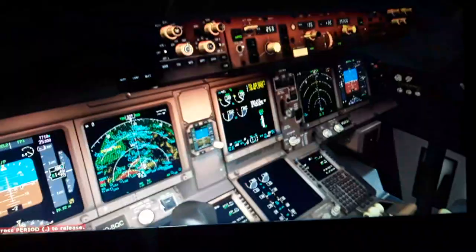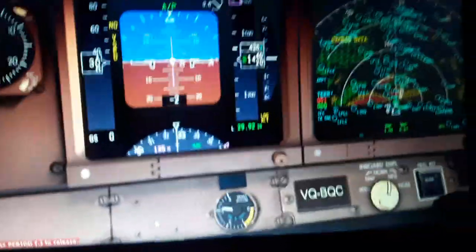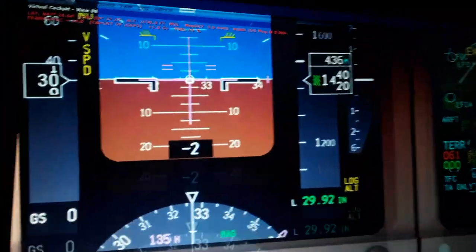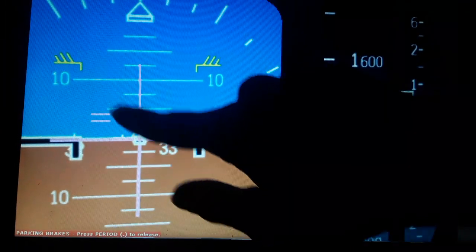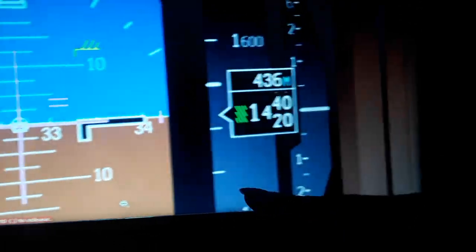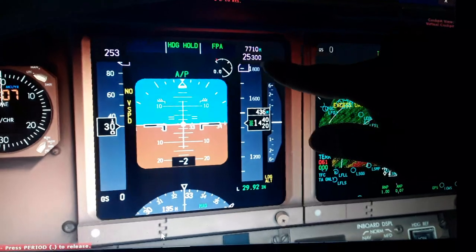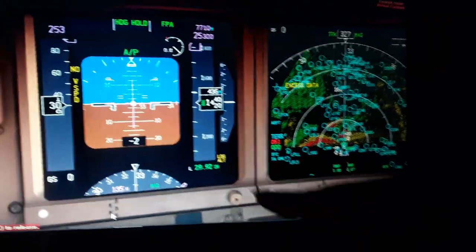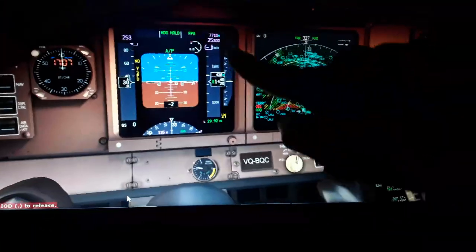So we have another positive over here, climb 3.5 degrees. You can see here +3.5 degrees, so it's a positive climb between the 2.5 and the 5 degrees. It's the altitude indicator. So this is gonna determine the flight path, 253 nautical miles per hour, 35,300 feet target altitude with the flight path angle, and this speed rate altitude. So you will see the needle moving up instead of moving down here in the vertical speed.